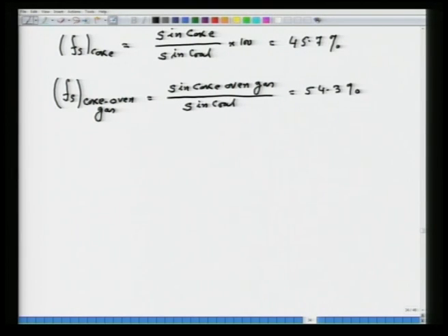Now, you have to calculate amount of air leakage. Now, to calculate the amount of air which is leaked, can you think of an element which does not react anywhere, or which is inert? Now, here say nitrogen is one such element that may react internally, say nitrogen may react with hydrogen, but NH3 amount is available to you in the output. So, if you do the nitrogen balance, then probably you can calculate the amount of air leakage, because input of nitrogen should be equal to the output of nitrogen. There is no other source of nitrogen except coal. Nitrogen is not coming anywhere had there been no leakage. But if you do input of nitrogen and output of nitrogen, you find some excess, and this excess has to be coming from the leakage of air into the coke oven.